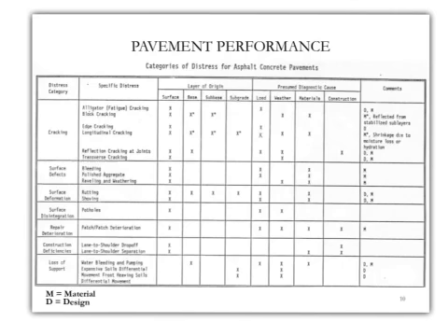Now if we take another example, the surface disintegration, which is the potholes that we talked about, the only layer of origin for potholes would be the surface only. Going all the way to loss of support, if we have water bleeding and pumping, this mainly starts at the base layer and then propagates all the way to the surface. While if I have differential movement from expansive soil, then it definitely has to start from the subgrade where the expansive soil is, and then it starts to affect the entire structure.